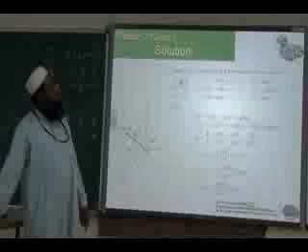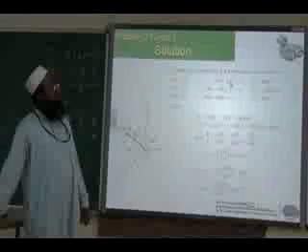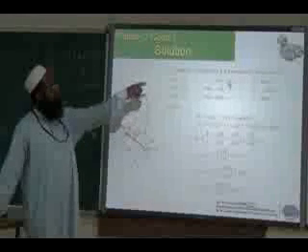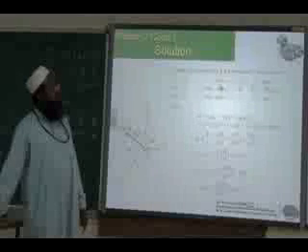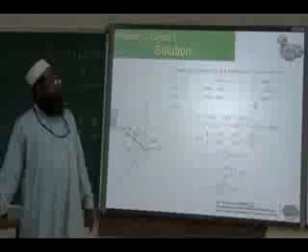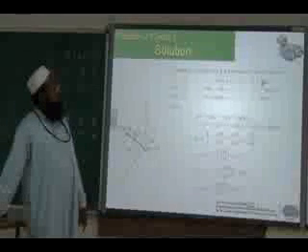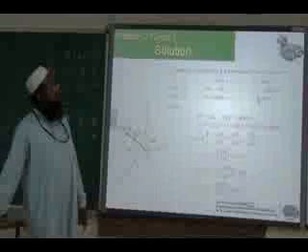Using the equilibrium equations, sigma Fx equals 0. So we find minus 200 for the I component. The I component is the Fx component, so we get Fx as 200. Fy can also be found, and Fz can also be found. If it is in equilibrium, the remaining part, the unknown force, is known.